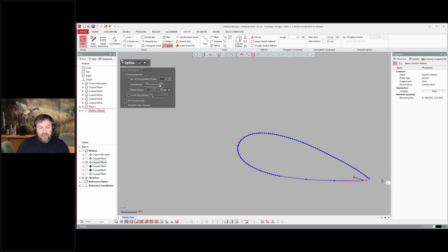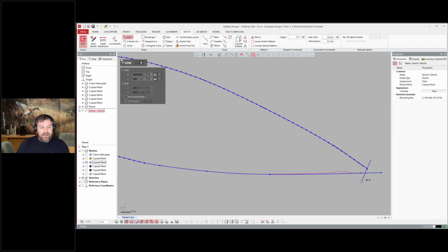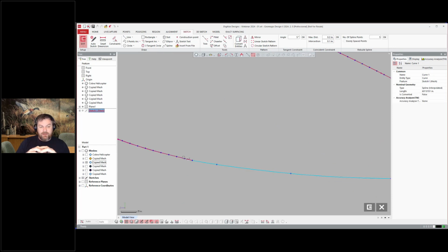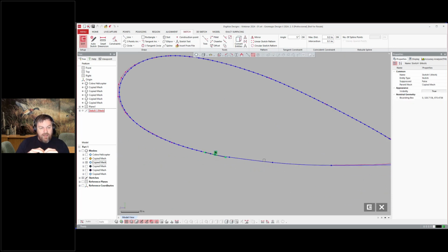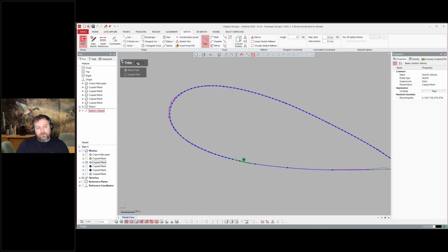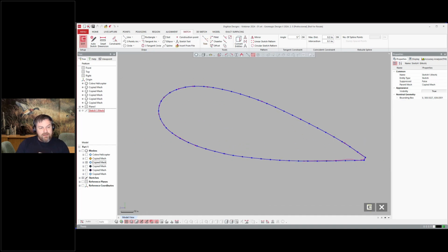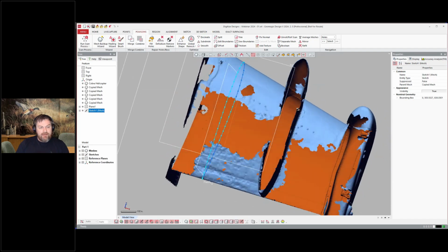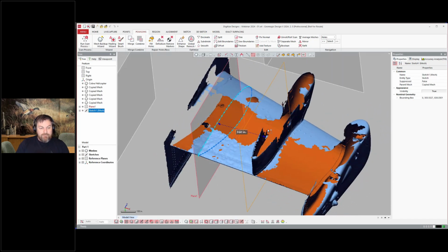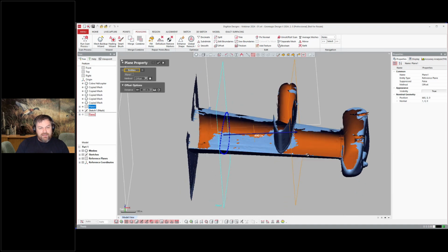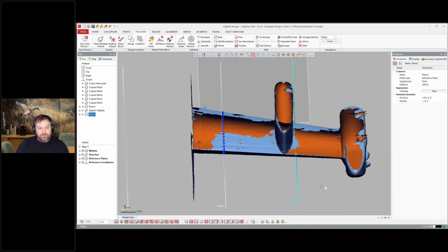And then areas that I may not have data, or maybe that is the area where the turret connects or whatever, I'm able to draw and CAD model directly over those areas on my own. And in this instance, what I'm just showing is we can cut a cross section, and we have that section called a mesh sketch and draw wherever we want over top of it. And this is a key component of Design X, being able to do that.